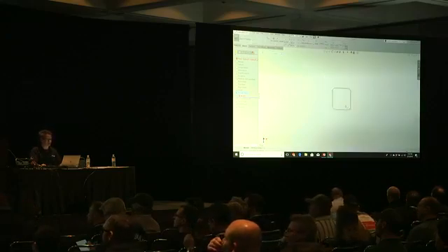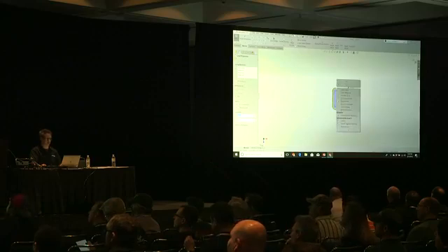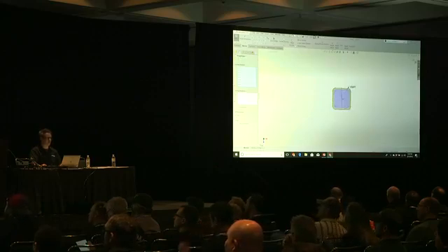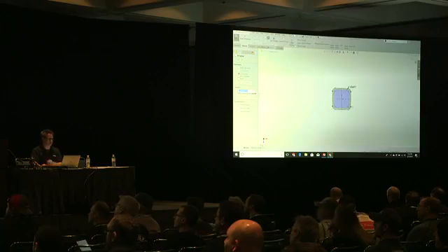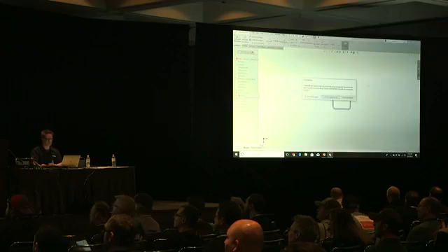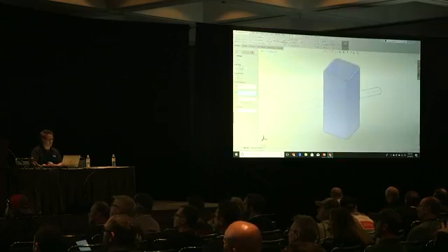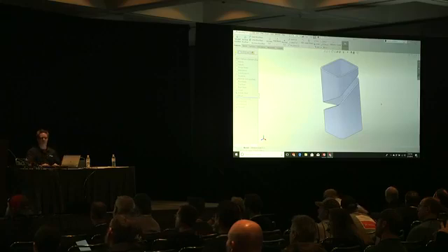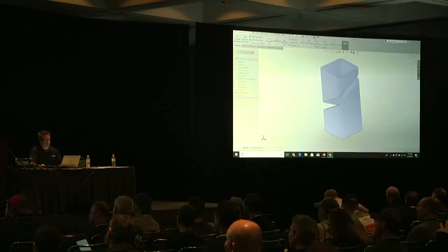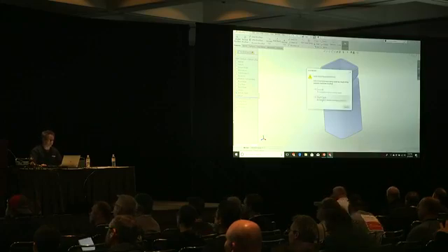So I'm going to edit my sketch. All you have to do, just like I did earlier, right click, select chain. There's a tool called Fit Spline. And what it's going to do is it's just going to wrap that around the part. Same error, we know what that means. Edit this, pick this face, and it's able to wrap it because that entire surrounding surface is one surface. So they took away one of my great tricks, but I'm really happy with spline surface, so I'm not going to complain.